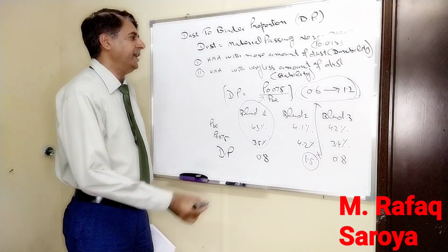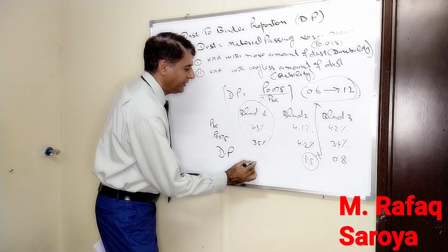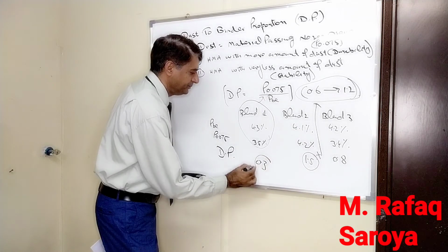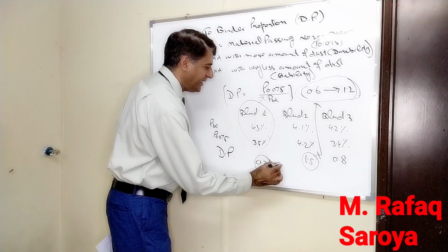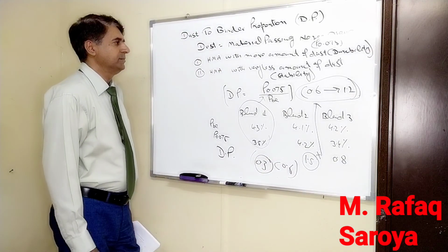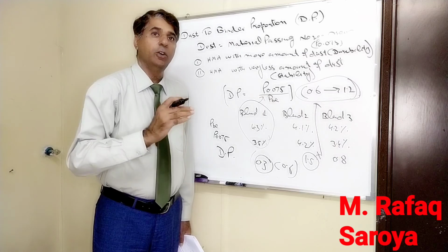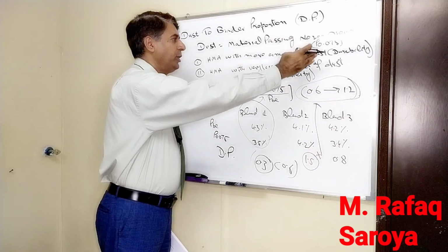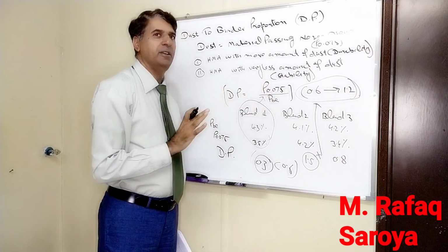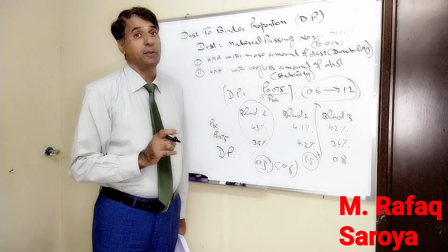And on the other hand, suppose I am going to get the value over here 0.3. It is less than 0.6, then the stability will be the problem. Clear it? Now if it is more, durability; if it is less, then it is the stability. And I have shown you over here, and it is very, very mandatory part of our Superpave Mix Design.